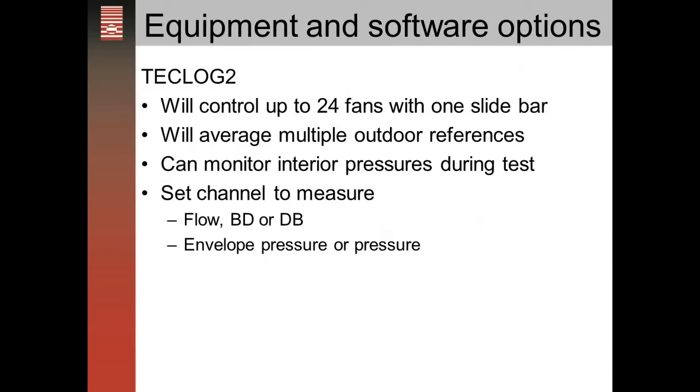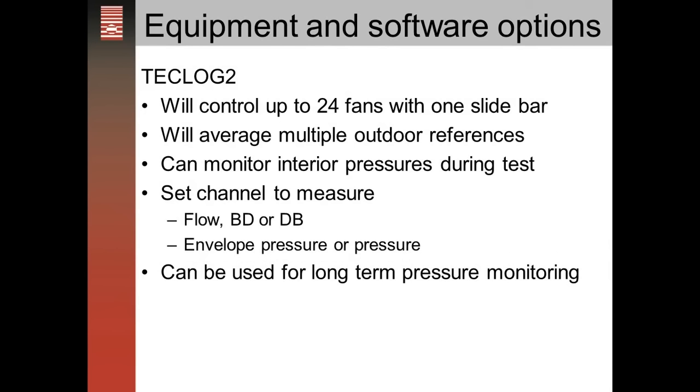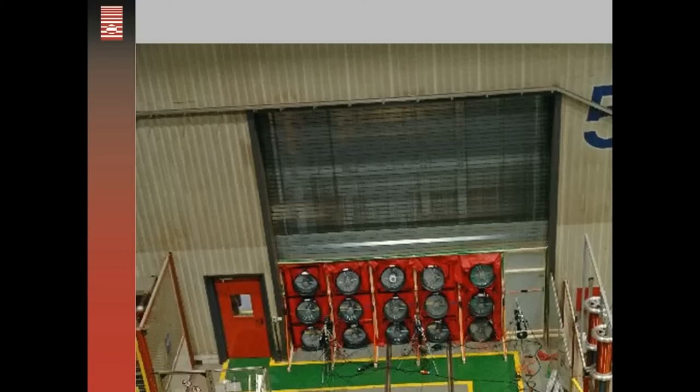You can set up each channel to measure flows either with a blower or a duct blaster. You could use it to measure envelope pressure, pressures within the buildings, or other types of pressures you may want to monitor, and it can be used for long-term pressure monitoring also. So you can get pretty creative on testing big buildings with setting up multiple blower door fans.